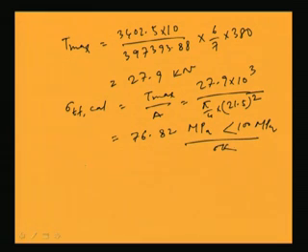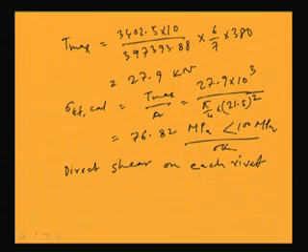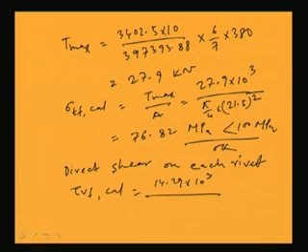And again, direct shear on each rivet has to be found out. That can be found as tau Vf cal is equal to 14.29 into 10 cube, because the shear force earlier also we have calculated this, as 14.29 by pi by 4 into 21.5 square.